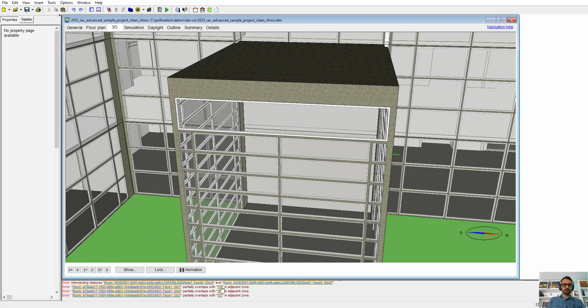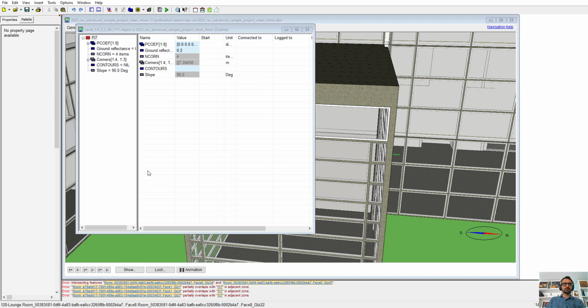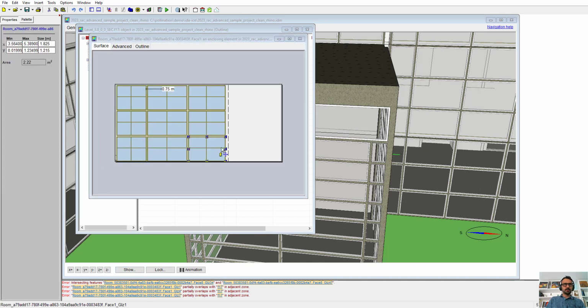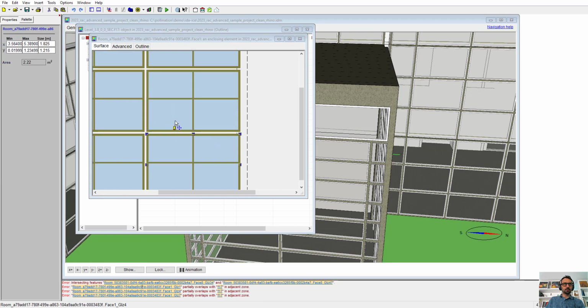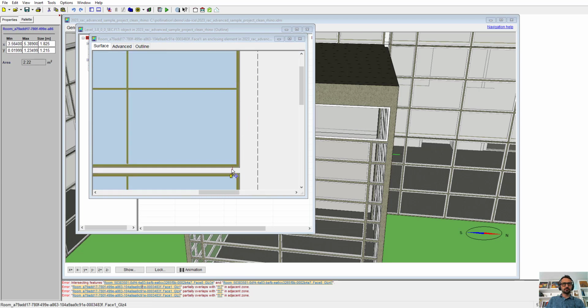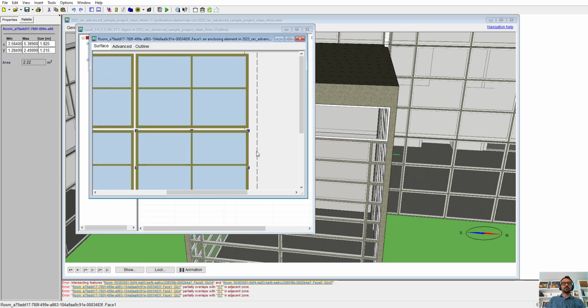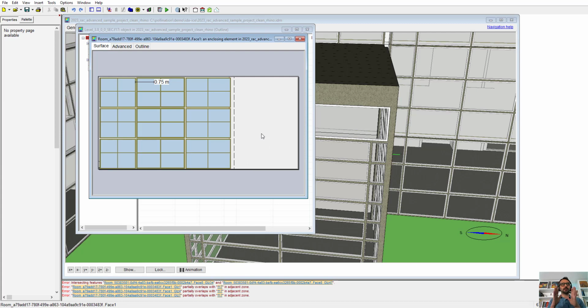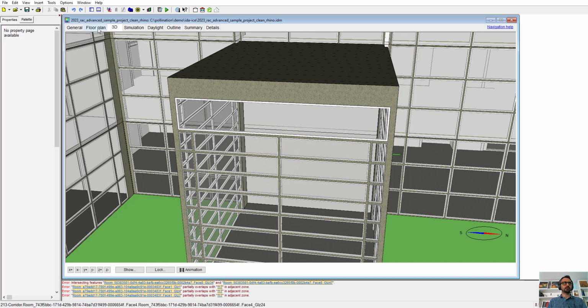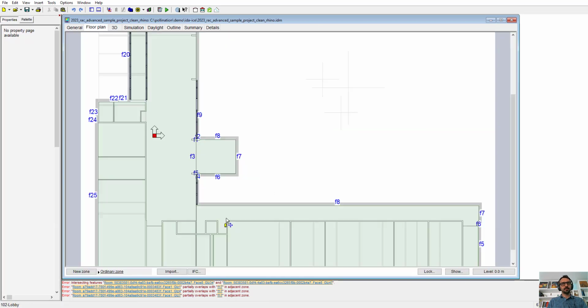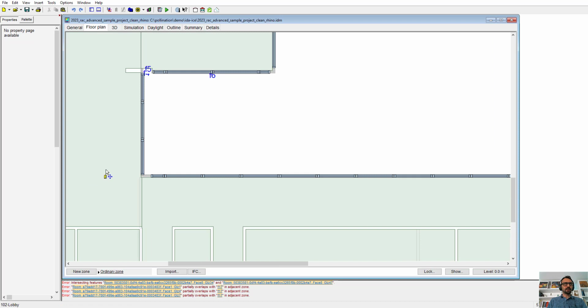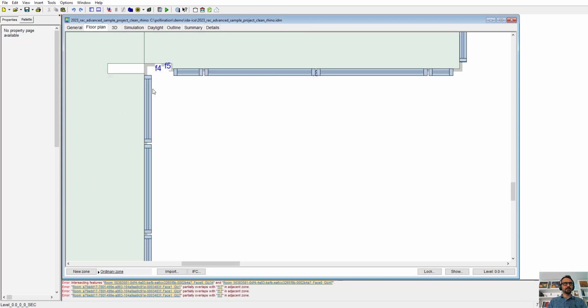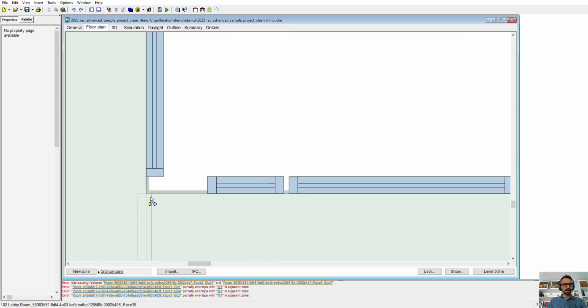Similarly for these ones, what's happening, if I click, is they are next to the wall, and because of wall thickness, so you see the line for wall thickness here, they are valid in a Honeybee model or Pollination model. But when it comes to IDA ICE, because it adds that wall thickness, and maybe this is a good time to go and check the floor plans, then it considers those as having an intersection. In that particular case, those are happening here because this was a separation line and we don't have that